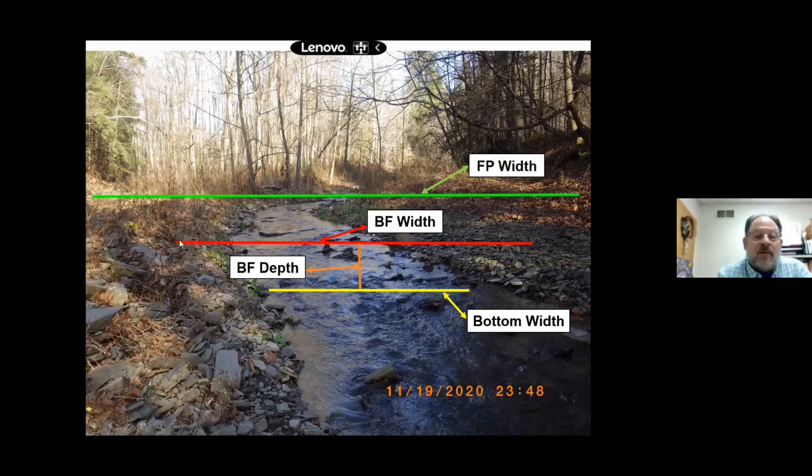And then we draw that same elevation across to the other side, where this channel here seems to be a little bit steeper. Most of our floodplain in this one looks like it's over on this area. So once we get our bank full width figured out and our bank full depth, we can then try to survey where our floodplain width would be.